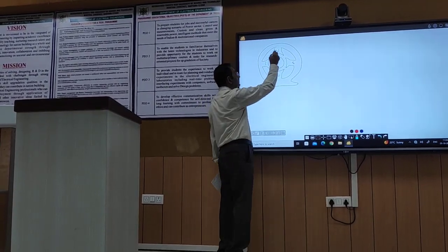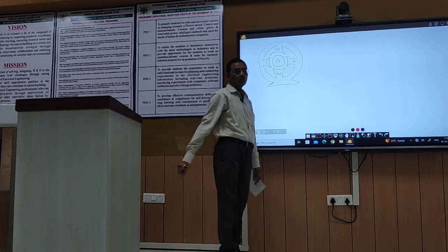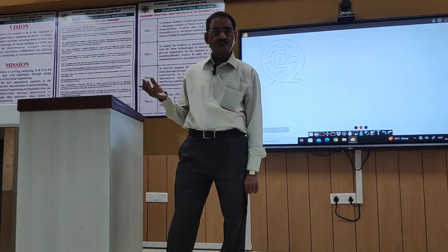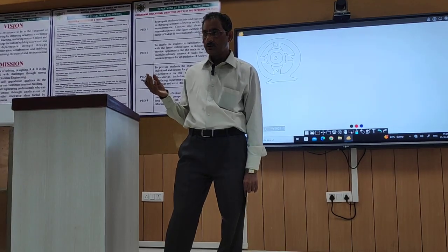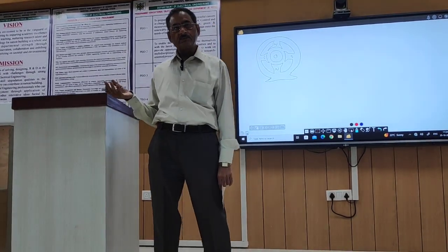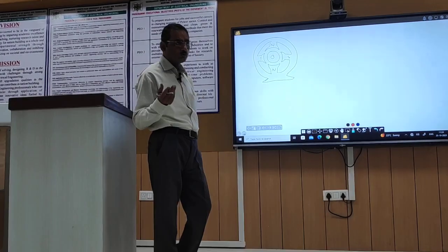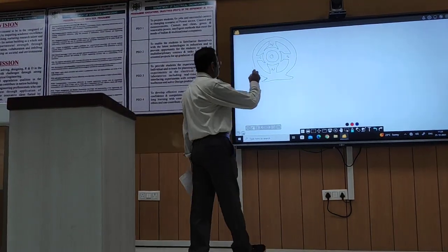Okay, field winding: these north poles and south poles can be either electromagnetic or permanent magnet. Most of the time they are electromagnets. So how can the electromagnet be formed? By providing DC current.